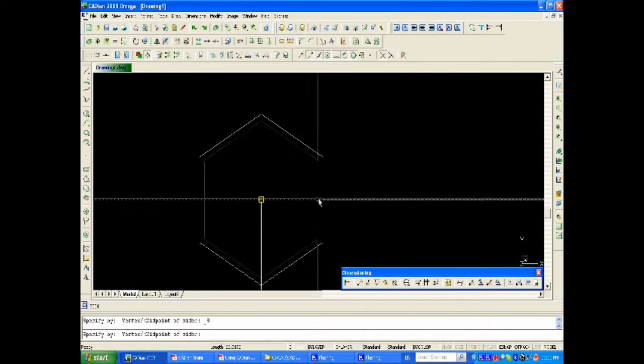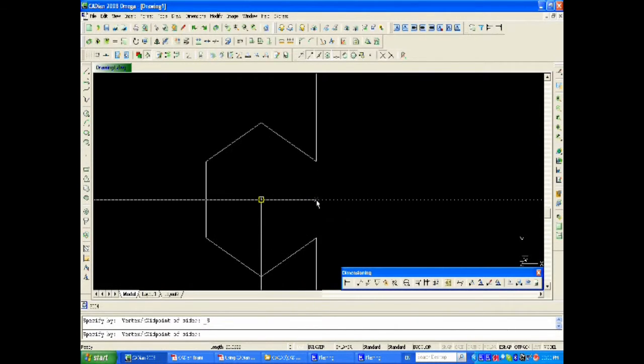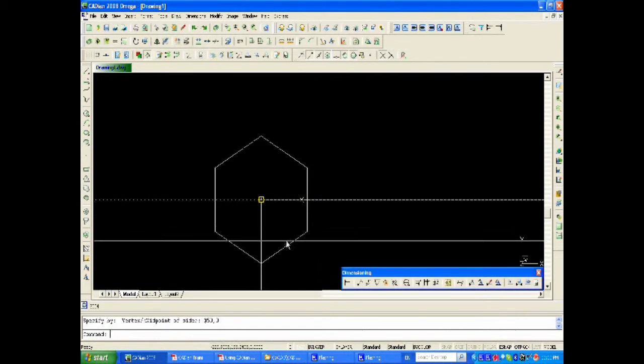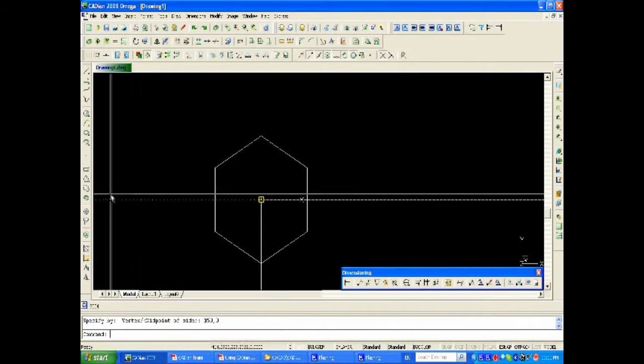Now, if I want, we call it across flats. If you look at the direction, it's the two flats on opposite sides, right? So I can say make this 100 millimeters across flats. That means I must go 50 mil to the right and 0 up. See what happens here. After I've drawn 50 mil to the right, the across flats dimension is 100 millimeters.